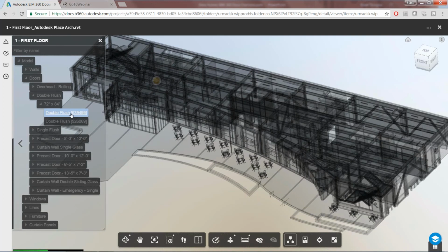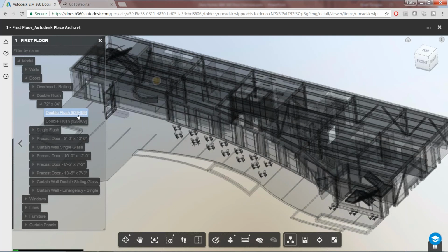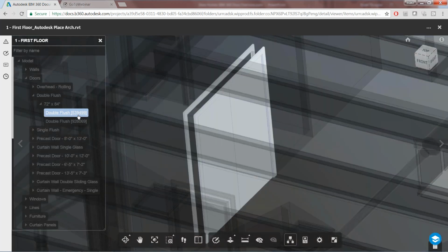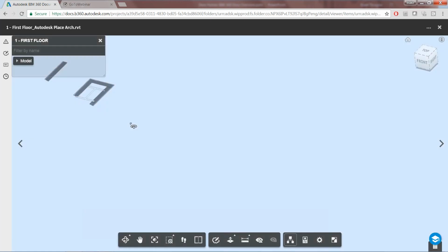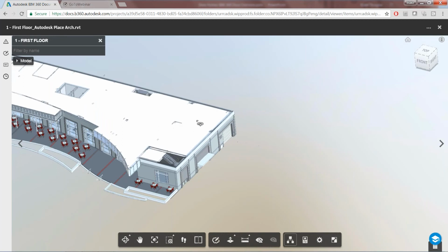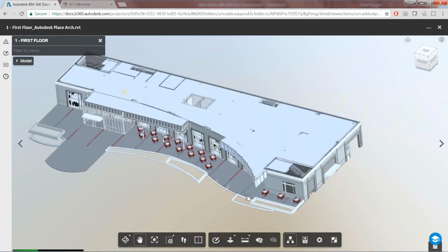And then if I want to pull a particular one with an object identification here, tag, say this is part of a door schedule, I can quickly come in here and select this. If I double click, it'll navigate me directly to that view. So quick, easy way to navigate the model and understand all the individual objects and everything that's happening inside of that model.